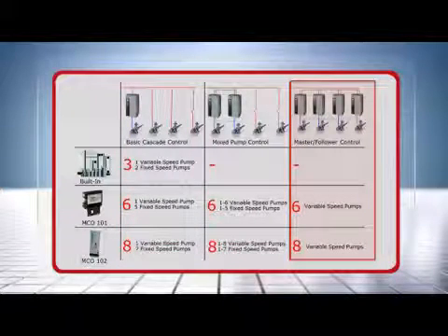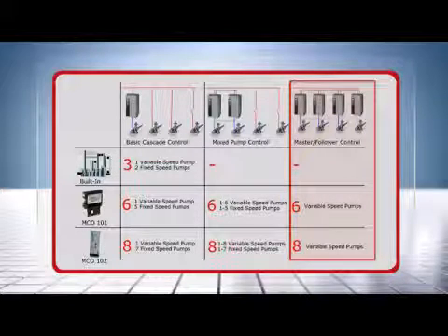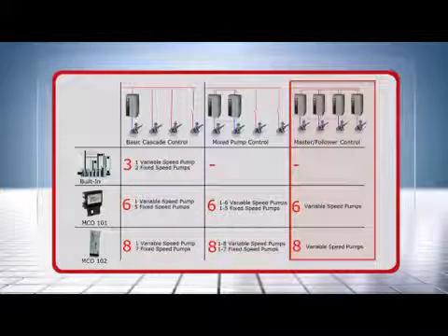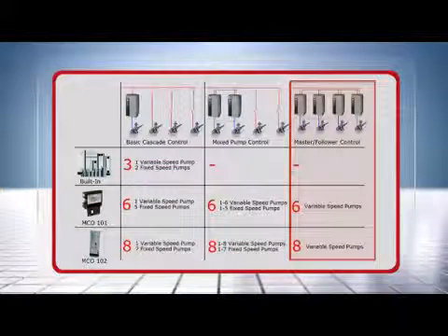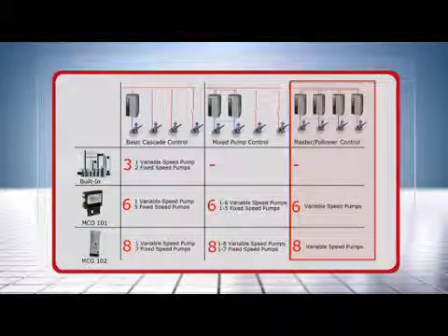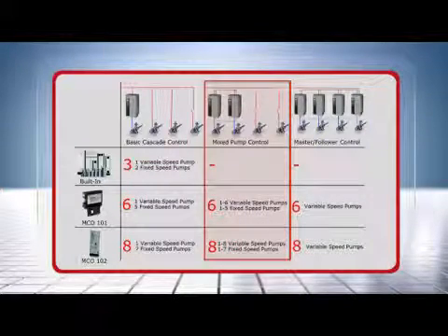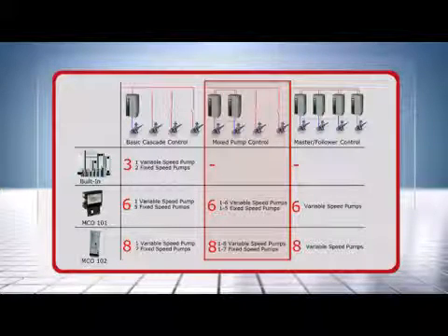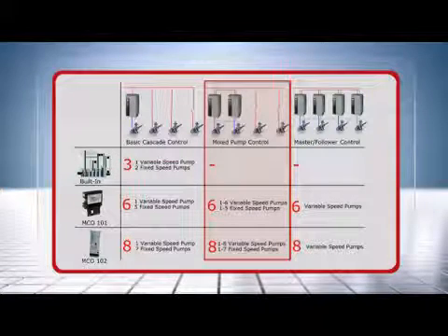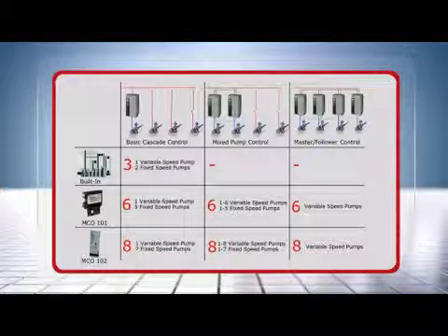For master follower control, each pump is speed controlled, meaning each pump is connected to a drive. Each follower receives its reference as a pulse signal from the master drive. The followers are started by means of relays in the master. In this application, all pumps run at the same speed. Mixed pump systems are a combination of variable and fixed speed pumps. The configuration also supports pumps of different sizes. Master follower and mixed pump systems require installation of a cascade controller option.